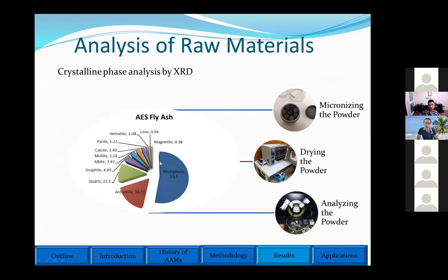So we learned that by introducing chemicals over an elongated period of time, for example more than 5 minutes, with a constant concentration, we get better dissolution, and then we could generate a very good alkali activated concrete with local AES fly ash.